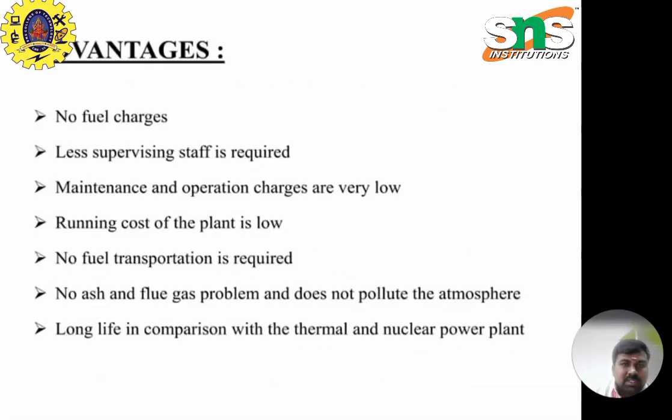These are the advantages of hydroelectric power plants. There are no fuel charges, because water is used as the energy source. It is naturally and abundantly available, so there is no need to pay for the water. Less supervising staff is required. The maintenance and operation charges are very low compared to steam thermal power plants, gas turbine, and other types of power plants. The running cost of the plant is also low.